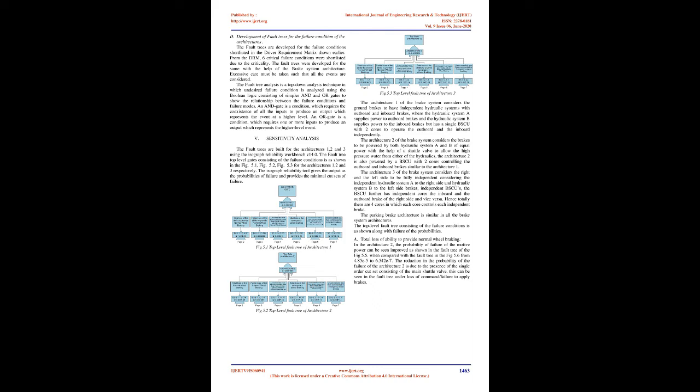C. Driver Requirements Matrix, DRM. The driver requirement matrix is also called the Preliminary System Safety Assessment Matrix, a few rows of which are shown in table 4.3. The critical failure condition is obtained by checking if the failure condition could drive other failure conditions. Only the driver conditions are considered for performing the fault tree analysis, since it is the worst case condition and is most conservative. This helps us keep track of the failure conditions, helps us get more accurate requirements, and reduces the time by avoiding development of fault trees for all failure conditions.